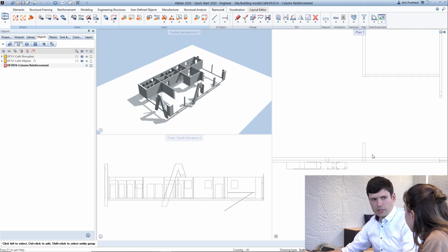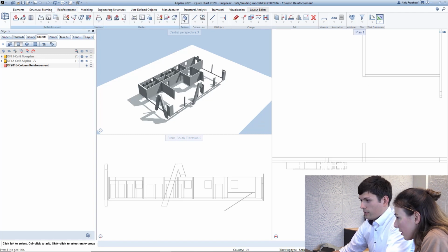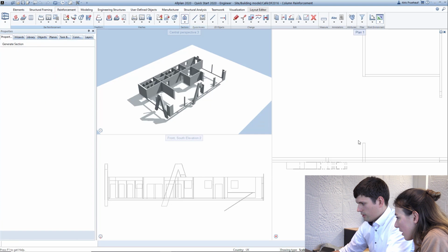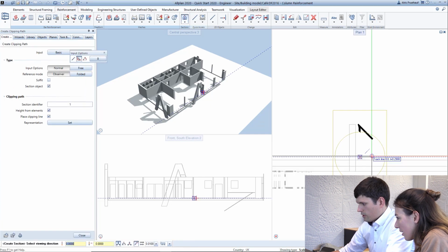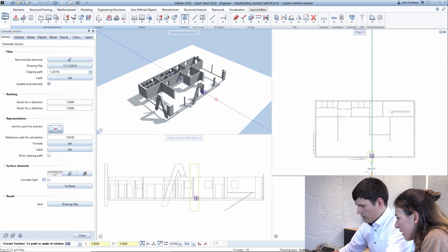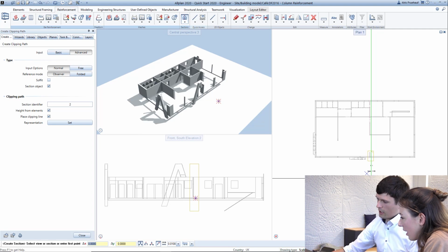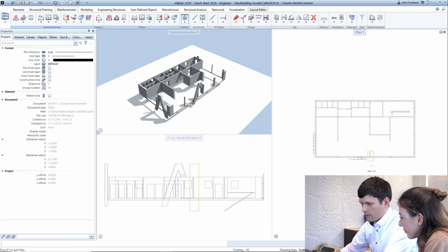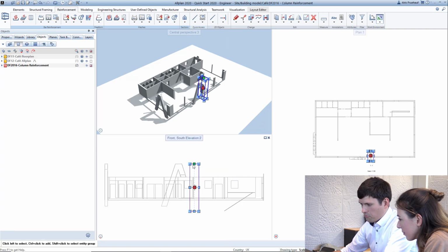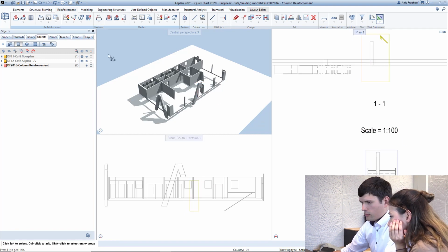The first step in rebar detailing in Allplan is creating a section, as everybody has done for years. Just create this little section here. I'll do it in a plan view, just a couple of steps, and place it right next to it. This is just a derived section. You can see it here as a section object. It takes the heights from the adjacent elements. You can also drag and drop it a little bit, and the representation could change a little bit. So it's just derived.